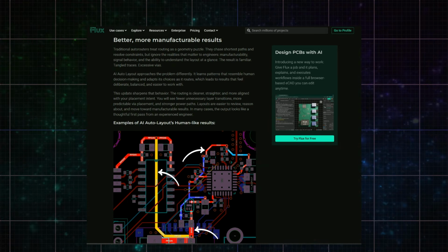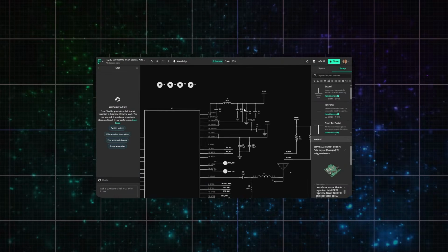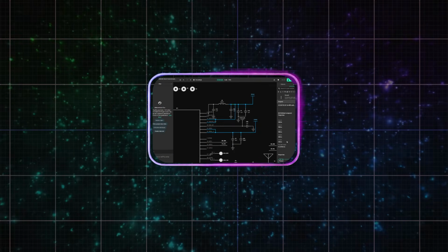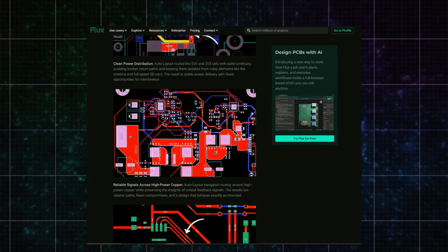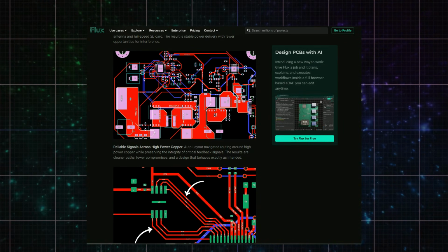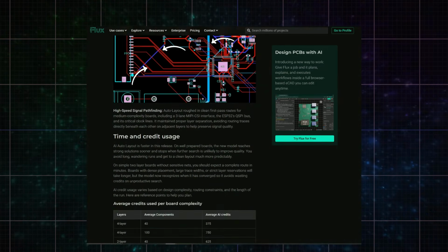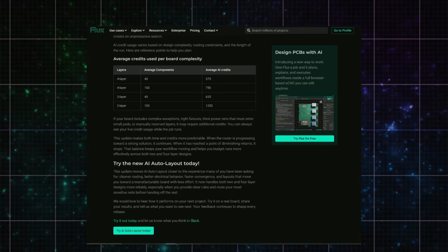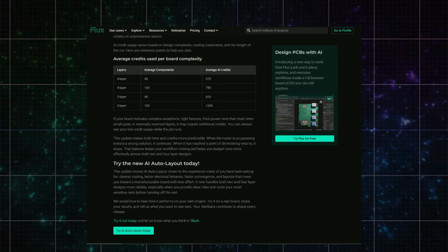These provide better context and feature support, like net types, where sensitive nets are routed earlier with cleaner separation and noisy nets are handled more cautiously. There's also relaxed clearance of traces, improving ground port continuity, which reduces crosstalk and improves signal integrity. Overall, the winter update makes AI Auto Layout faster to use, cleaner in its routing decisions, and more dependable on 2, 4, and 6-layer boards.